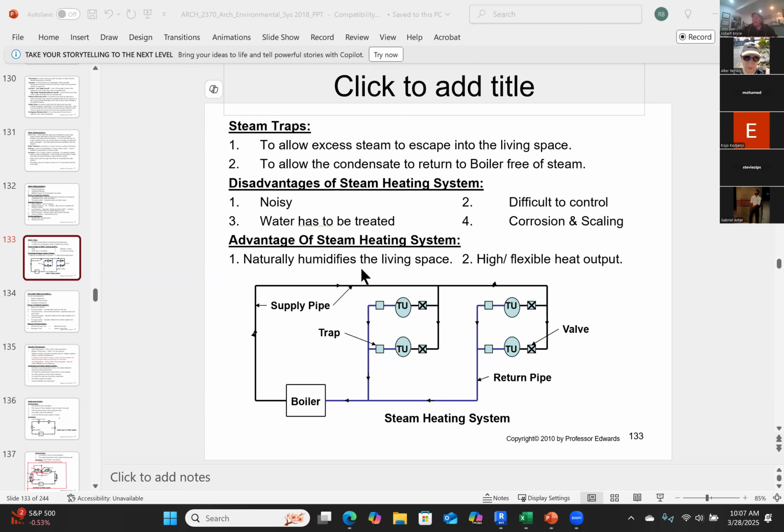And then as you go outside of the range of the temperature, that would send a signal to this valve and it would open it up again. Or alternately, you might just have a valve in your space. And when the heat in that particular space becomes uncomfortable or comfortable enough, you might just go over and turn the valve off, which stops any steam from going into the terminal unit.